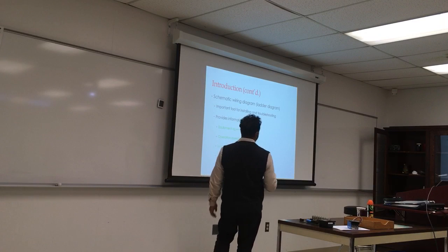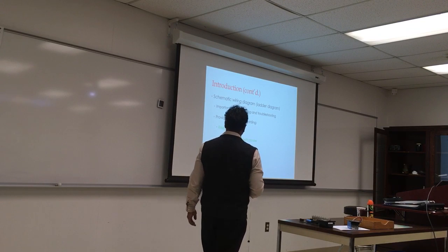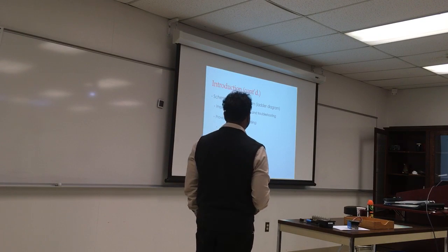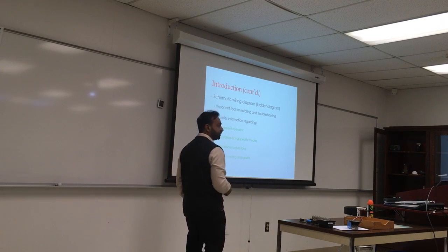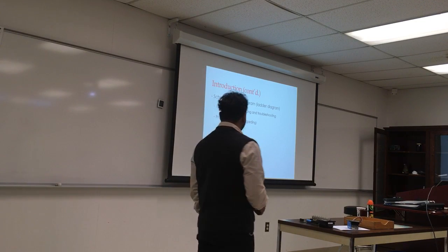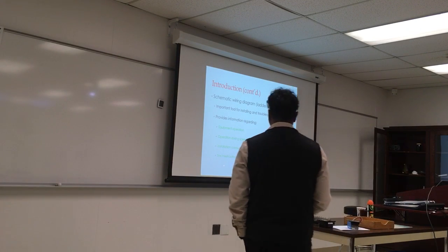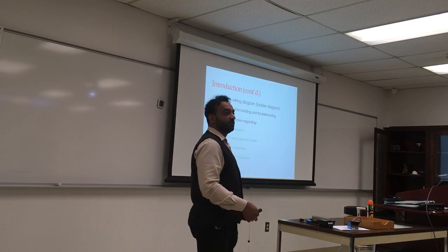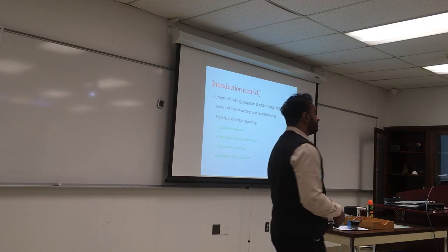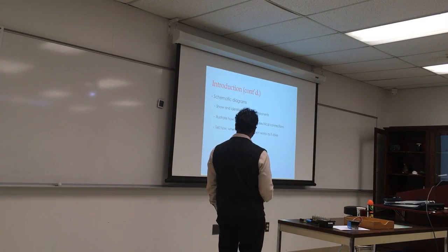So there is something called the ladder diagram. We saw that last class, where we go from the line voltage and step down to every piece of equipment. A schematic is for installing and troubleshooting, and provides information regarding equipment operation modes based on the switches; installation connections, meaning how things are connected, whether in parallel or in series; and troubleshooting and repair. If something goes wrong, probably there's some indication light, or it will show you what might have gone wrong. Components: how do they work?